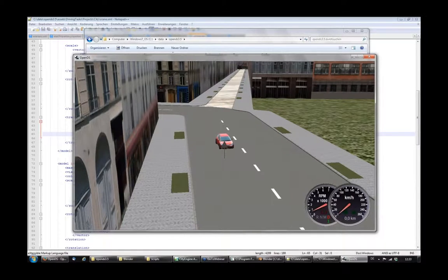I showed you how you can export your models from CityEngine. This can be done using the OBJ exporter of CityEngine. This again could be opened with Blender. However, you have to take care to use Blender in the old version 2.49b. You have to install Python in the same version as your Blender version has been compiled. You have to download the ogre.scene exporter and the ogre meshes exporter. You have to copy both of them into the Blender plugin folder where all the scripts are located.